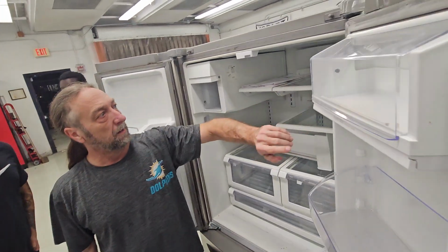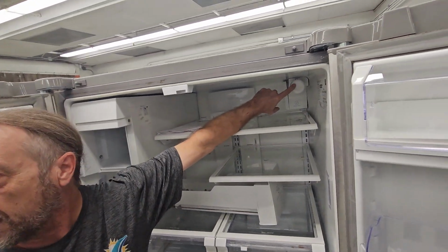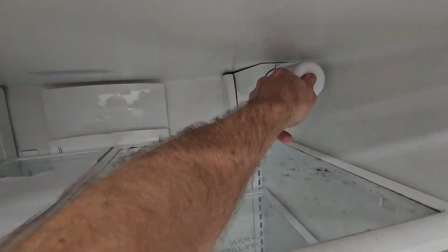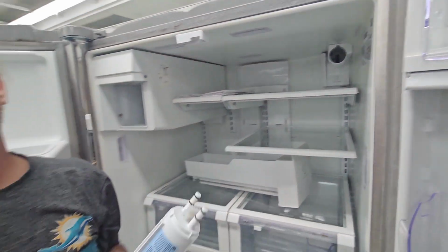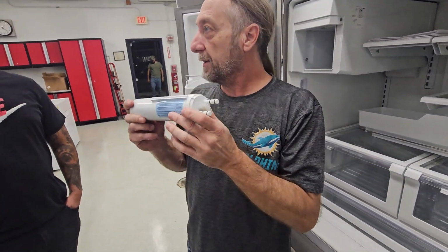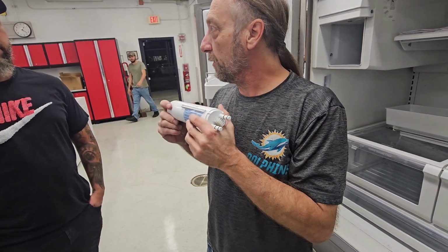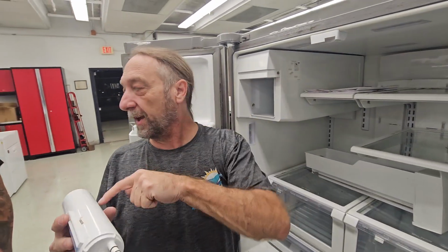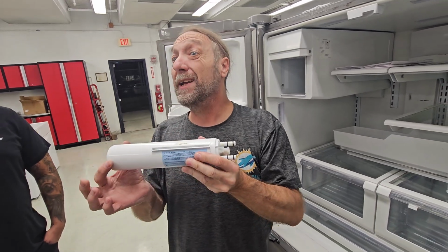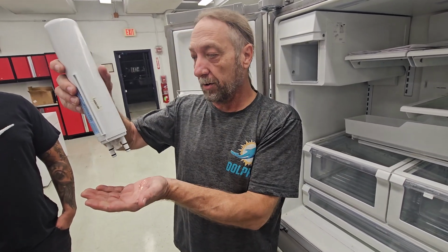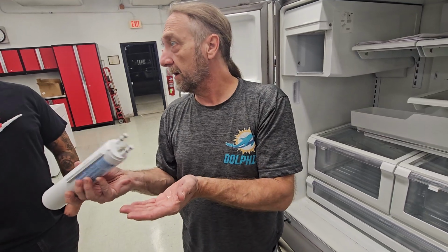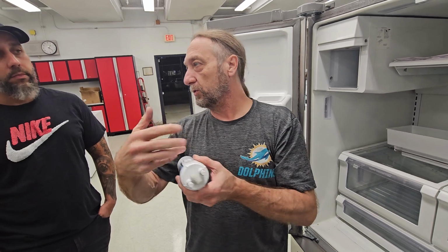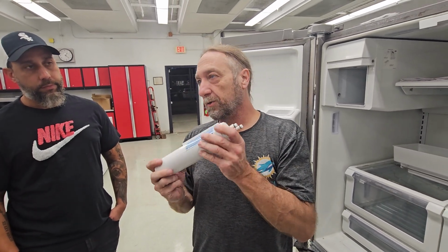Oops, sorry. You're good. So that line that came out of the water valve, like I showed you in the drawing, goes immediately to the water filter, and Frigidaire just makes it so you push it in and it pops right out. Okay? On the side-by-side Frigidaires, I saw that a few of them had problems. Like there was a wall here from the freezer cools the fridge, that the cold air was hitting the water filter and freezing the water filter. You got to see if water comes out. Okay, you can hear it. That when you change the water filter, you have to run a few glasses of water to get the loose carbon that's in here out. But you also want to make sure it's not frozen.